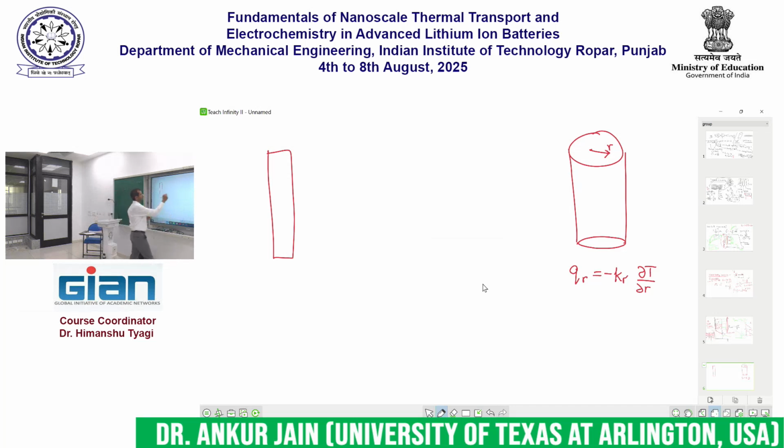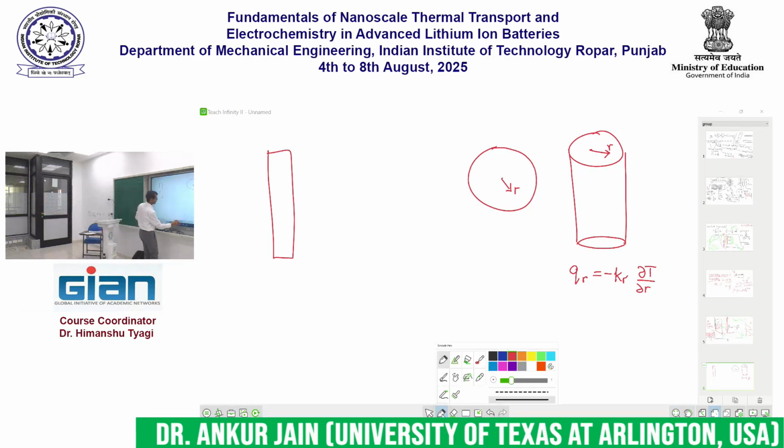Here is my cylinder. Let me show you the top view. This is the center of the cylinder. What is the easiest location for me to stick a thermocouple? On the outer surface. Absolutely. So here I place one thermocouple. Where do I place the second thermocouple? No, there is no point of placing a thermocouple on the opposite direction. That doesn't help me, because these 2 thermocouples are both at r equals R.